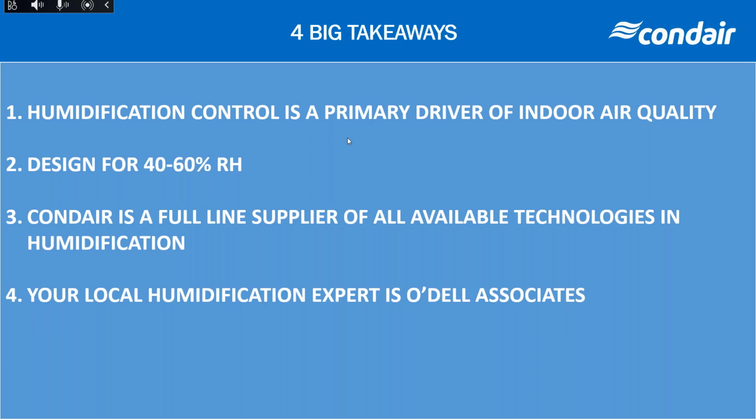So the optimal relative humidity range is the same. And as you know, relative humidity takes into account temperature. We just had somebody asking about meat preparation facilities, saying that it's very hard to keep the relative humidity in that range because it's so cool. But anyway, relative humidity incorporates the temperature, so the 40 to 60% is a critical sweet spot there.